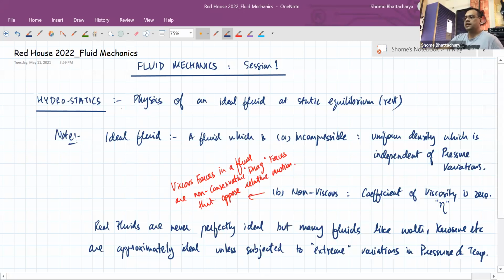It's a unitless, dimensionless physical constant, whereas coefficient of viscosity has physical dimensions. It's not dimensionless. And in that sense, viscous force is different from frictional force, because the amount of viscous force depends on the amount of relative motion, whereas kinetic friction does not depend on the relative velocity. It just depends on the coefficient of friction, that is the material, and the normal contact force.